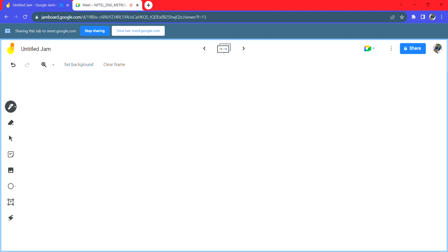So let us say I have a box like this, which is totally sealed, and here I have a plate of a capacitor and this end is fixed. This cannot move, and this is the first plate of the capacitor which is subjected to forces, and this is made up of elastic materials just like diaphragms, and all over here filled is the dielectric.